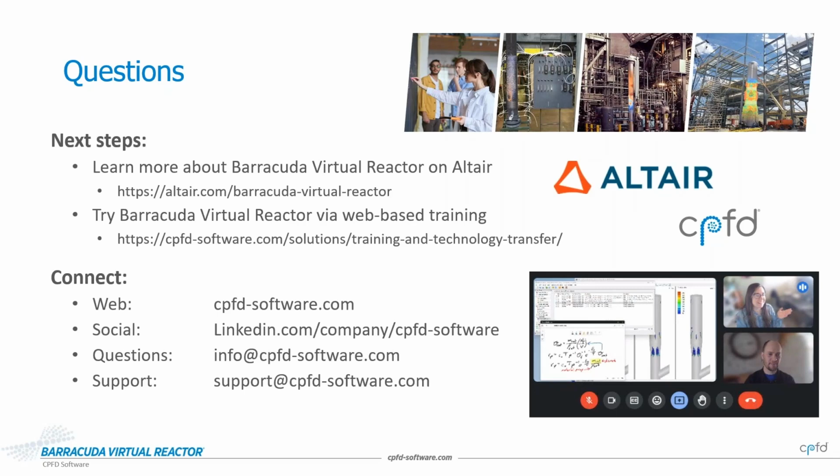The last thing I'd add is you can physically connect them, like with that standpipe, but in some cases you might want to virtually connect them. So in the same Barracuda virtual reactor model, you could have vessel 1 and vessel 2, but instead of a physical connection, you can have an outlet from vessel 2, track what's leaving there, and use the boundary conditioning connector feature to say the particles that leave here are entering over here without modeling that transfer line. Yeah, you can even put a filter function on that. Maybe that goes through a cyclone first, and the fines are lost, and the other ones come back. So it's all possible. It depends what you want to accomplish with the model.